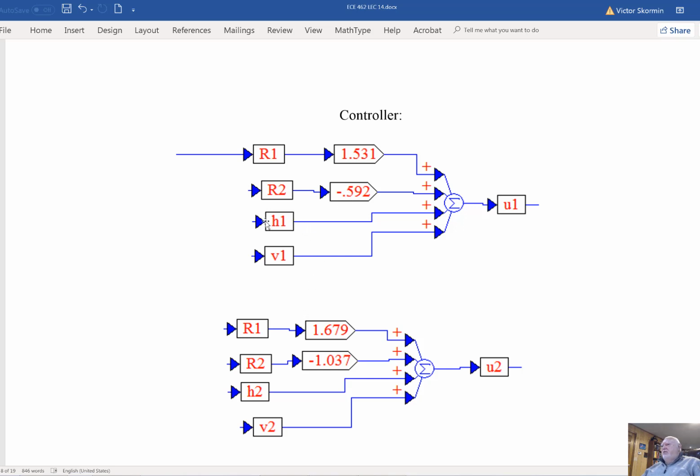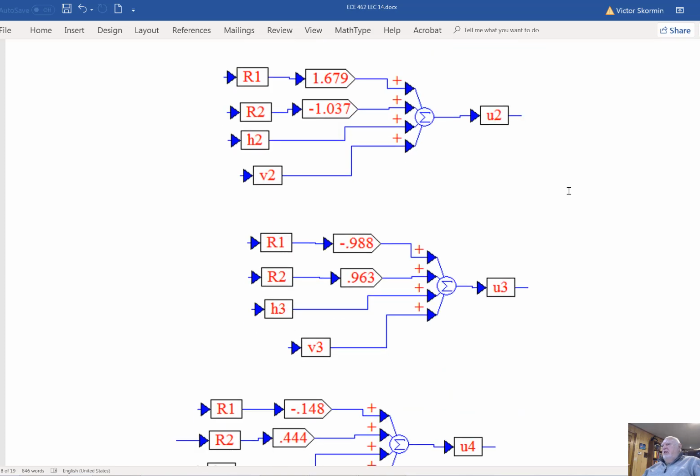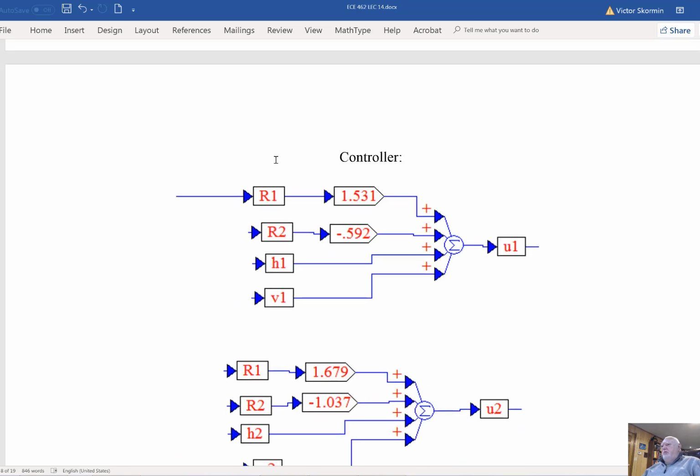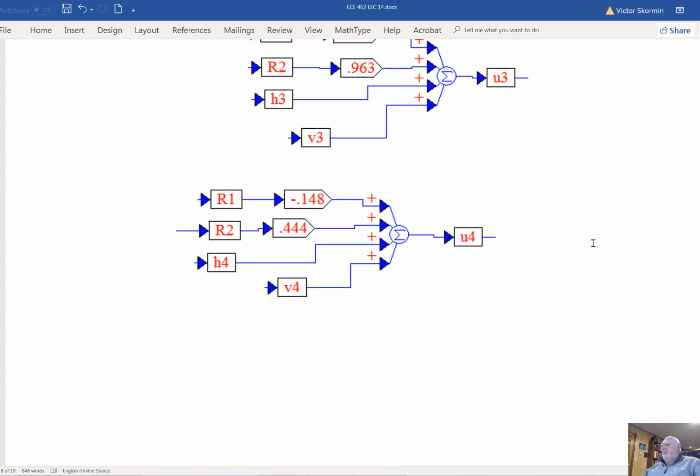Then I have this state variable feedback injected, and I have one of the components of the vector Km times x. So this is the control law. The control law has 2 inputs, reference 1 and reference 2, and it has 4 outputs, because the control law is responsible for generating 4 control efforts applied to the input of the plant.